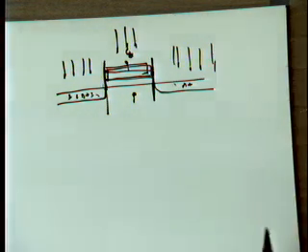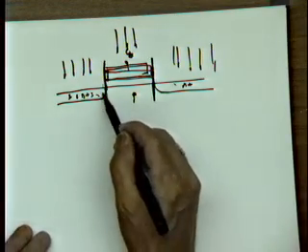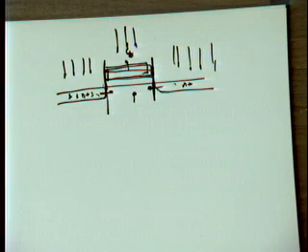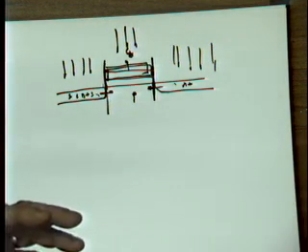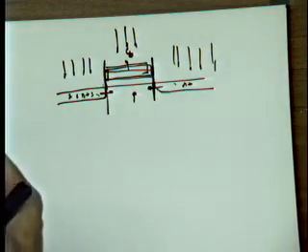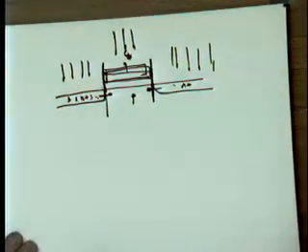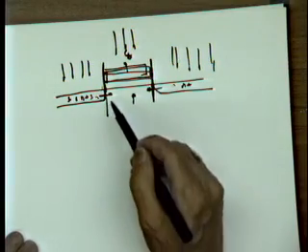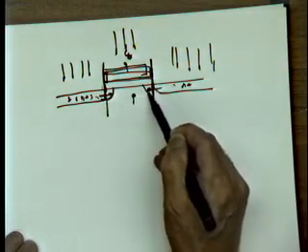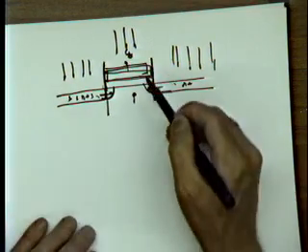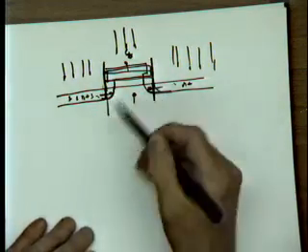I put the thing in the oven, and what's happening is these N plus parts start to diffuse, like they always like to do. There's a P here, there's N here, you heat it up, the impurities start to move to areas where there's less of them. So that's what causes the overlap capacitance. The under diffusion is that this region extends a bit underneath the gate. Okay? And that's what your overlap capacitance is.